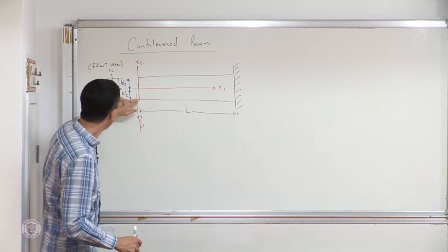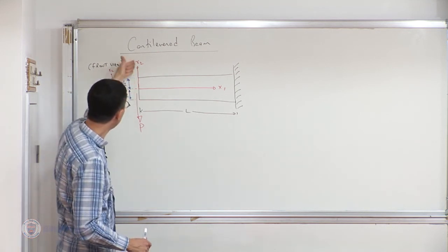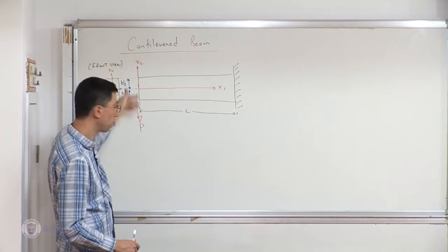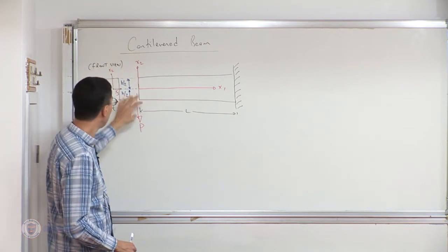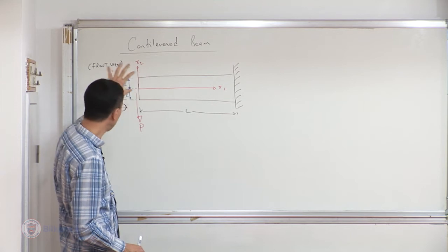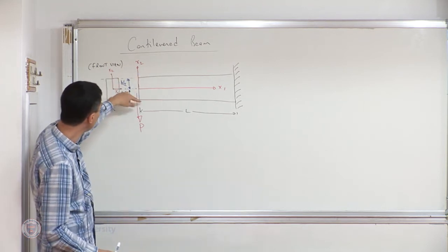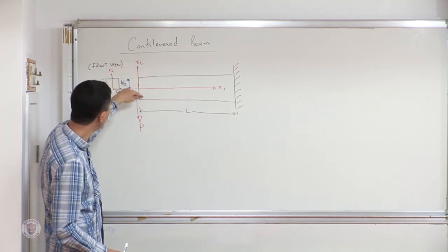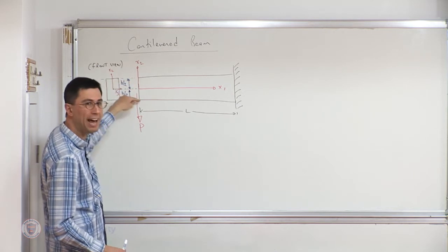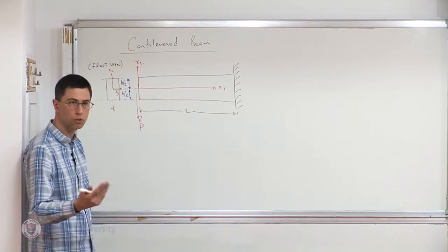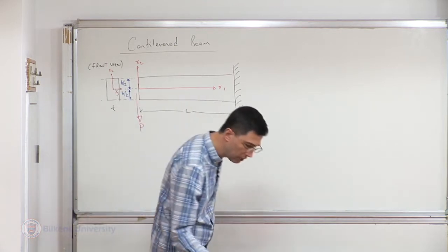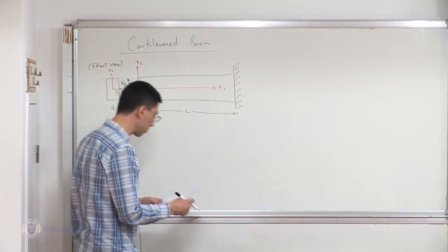Okay? So even if the actual distribution is not a pure shear stress distribution that results in that, even if there is something else, it is statically equivalent to that representation, and all the effects due to a more complex distribution will be an end effect on that surface associated with Saint-Venant's principle. I don't really care what the exact distribution is.